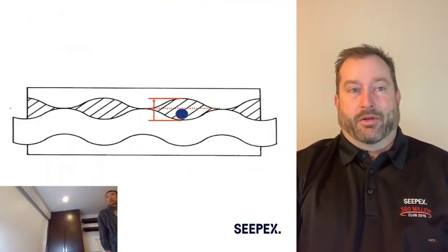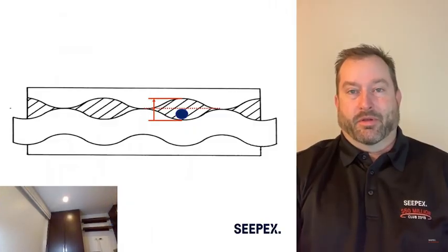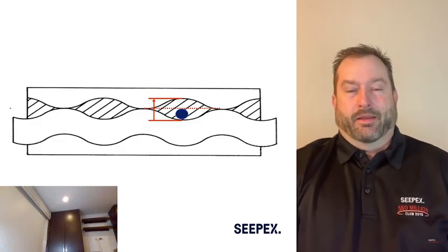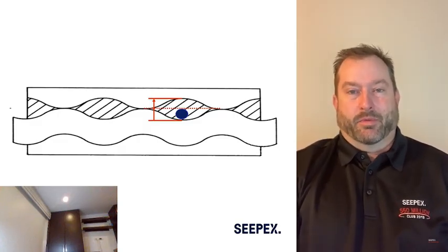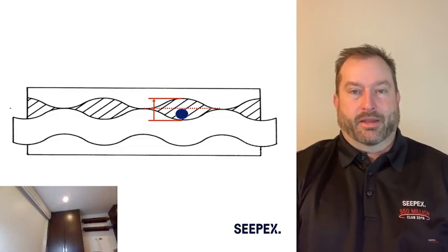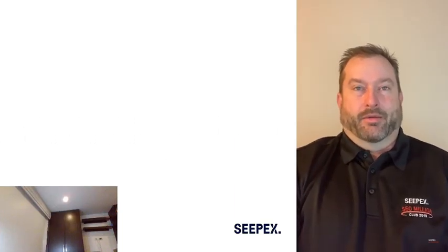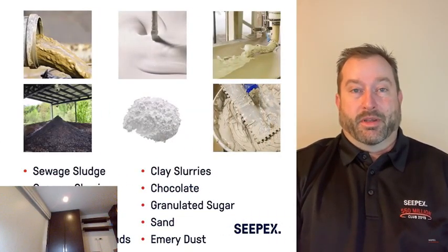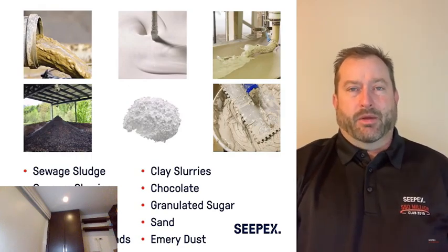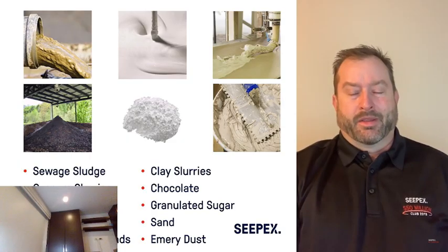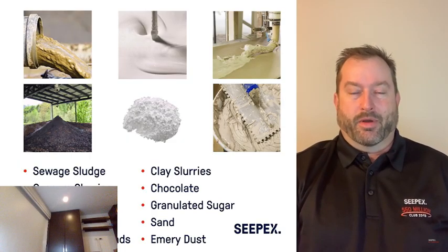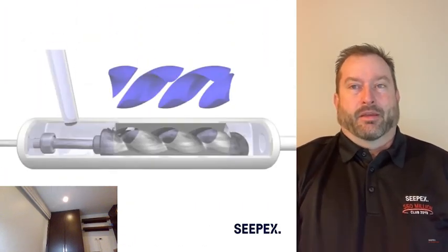Again, the pump can handle large solids, as we mentioned, as high as 4 inches on some of the larger pumps. And because of the way the cavity is formed, when those solids are trapped in the cavity, you see very little damage from the pump. The pumps are used quite often on abrasive fluids. We pump everything from calcium carbonate slurry, lime slurry. Products that have quite a bit of solids in them.